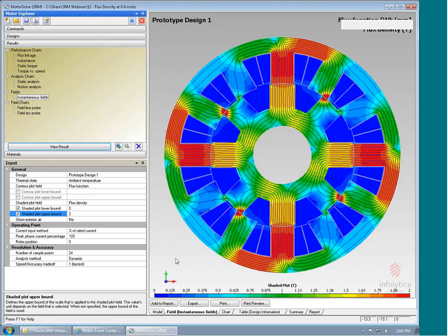And to do that, I have plotted two things in this graph. The first I'll call the flux function, but it's basically the flux lines associated with my various poles. And you can see that along with that, when I have a very high density or concentration of those lines, my color, which is up in the area of 2, changes consistent with the flux density close to 2 Tesla. I've set the range purposely from 0 to 2 for constructive assessment as we look at things.